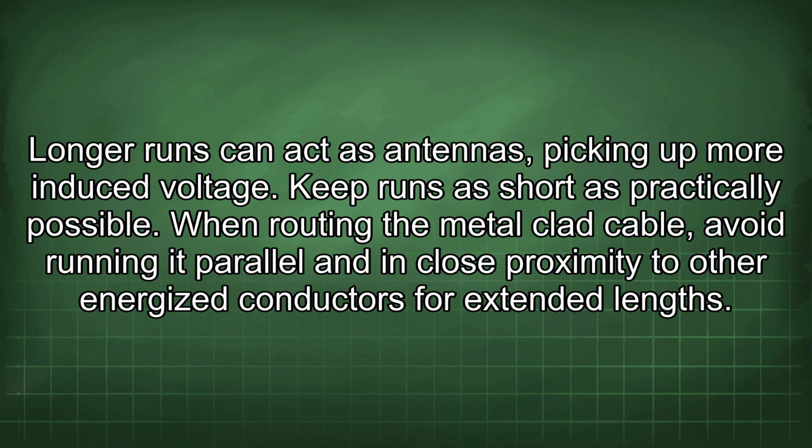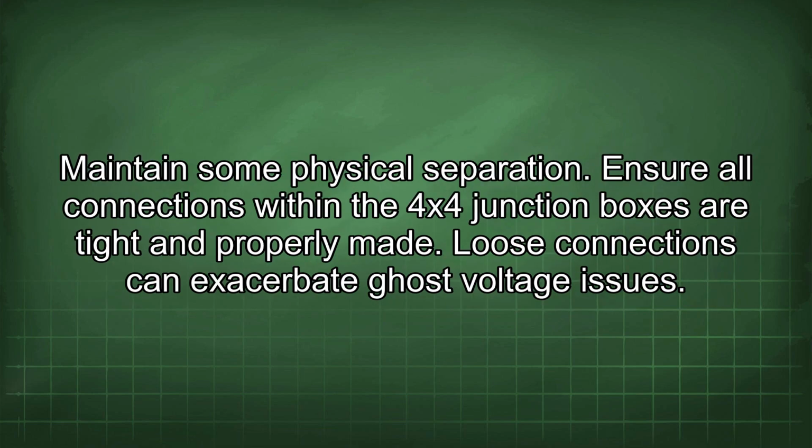When routing the metal-clad cable, avoid running it parallel and in close proximity to other energized conductors for extended lengths. Maintain some physical separation. Ensure all connections within the junction boxes are tight and properly made. Loose connections can exacerbate ghost voltage issues.